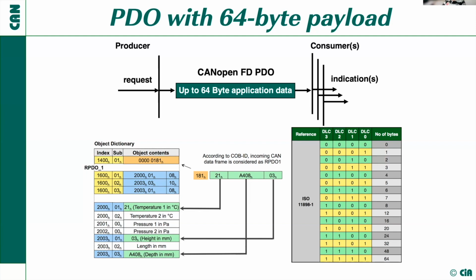One thing that you should consider, as I've said already: CAN FD frames cannot be enlarged in a byte-wise granularity, but only in certain steps. You see them here in this box. And I would recommend not to communicate any rubbish that is currently in the memories when you don't fill up to the next supported frame length. So for example, if you have just 18 bytes, the next one would be 20. So what about the remaining 2 bytes?